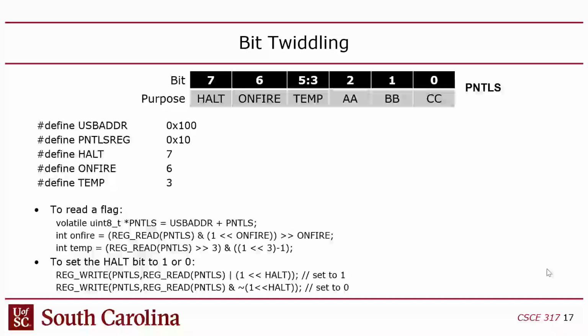You see that volatile keyword? If you declare a pointer in C as volatile, it doesn't mean anything for the C language, but the compiler will look at that and say, okay, if he declared this pointer as volatile, he probably intended this as an I/O load, so I'll bypass the cache. Because otherwise, if you don't bypass the cache, you try to write into a peripheral, and the peripheral never sees the value you wrote because it got caught in the cache. You cache the value instead of actually sending it to the peripheral.